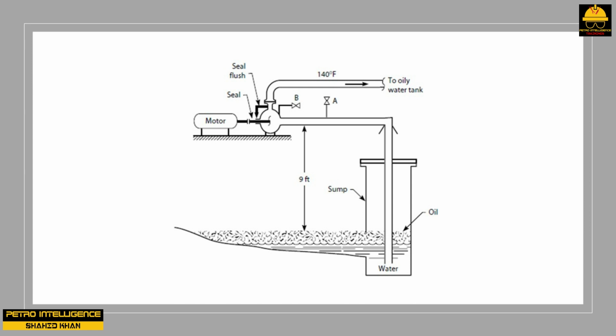To fix this problem in the refinery, the engineer connected an external source of seal flush water to the pump from a nearby wash water station. Pumps that have subatmospheric suction pressures and that are not in continuous service should not be self-flushed pumps. They should have an external source of seal flush material connected to the mechanical seal. With the external source of seal flush, the pump no longer lost its prime when shut down.